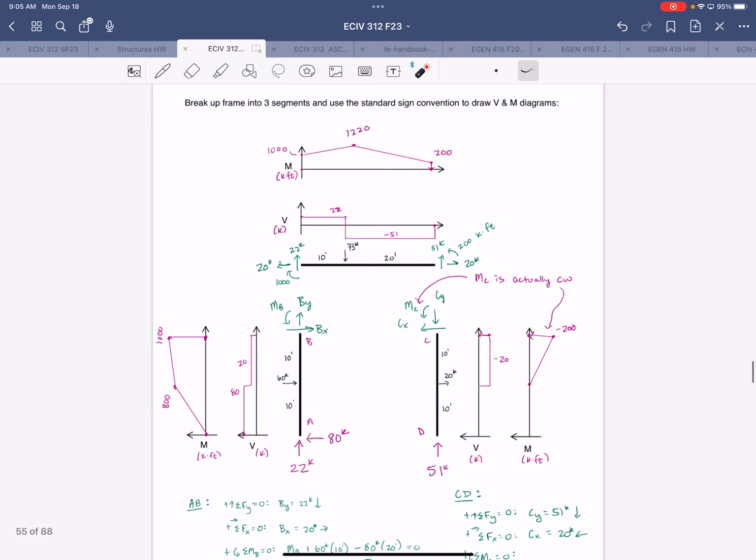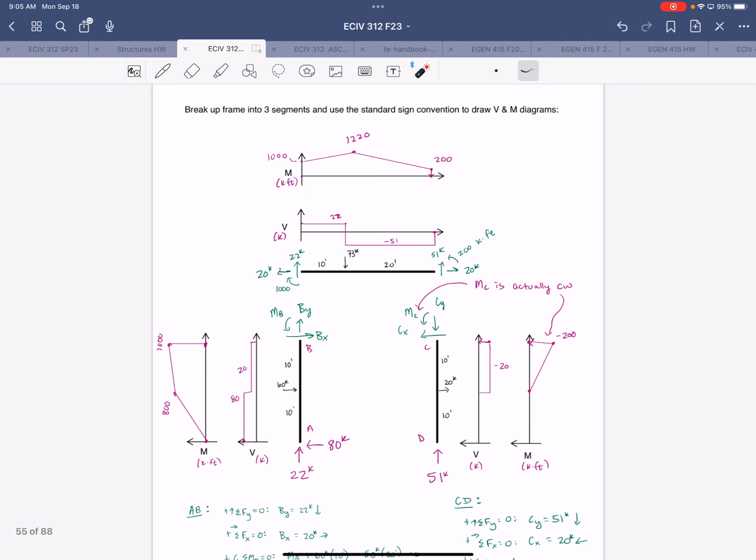Now, if you had done that and maybe found that the shear or moment diagram doesn't close, then that's a sign that you maybe got something wrong with those joint forces, all right? Or maybe you missed something in the transfer, because remember, it's equal magnitude, opposite direction whenever you transfer forces from one joint to the next or from one side of a cut to the other.